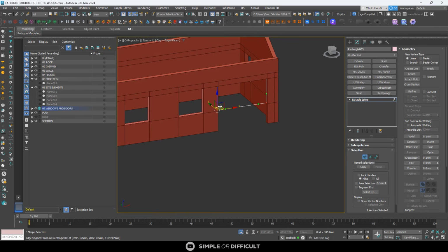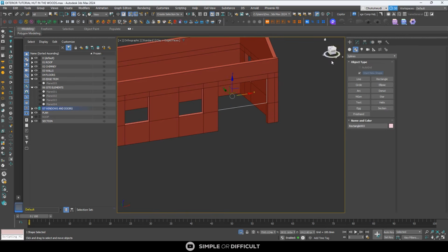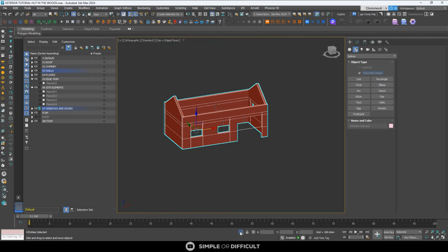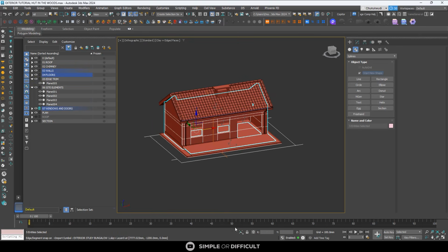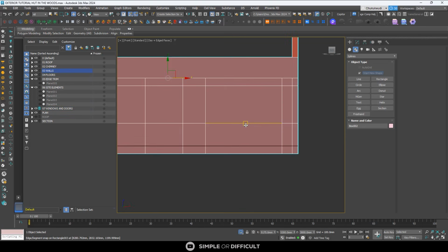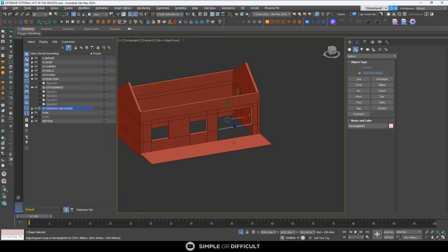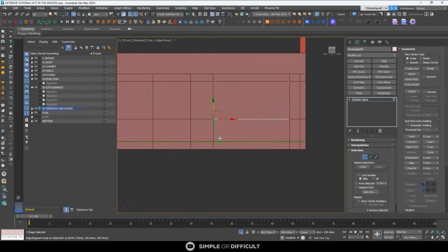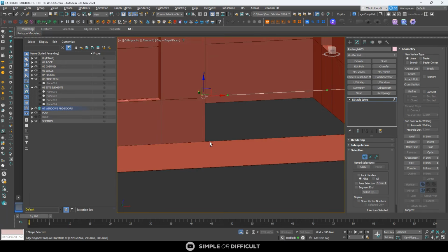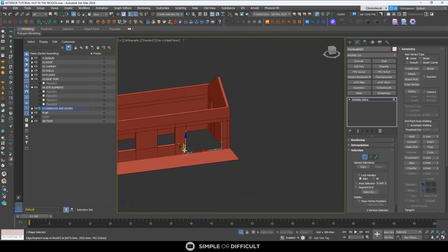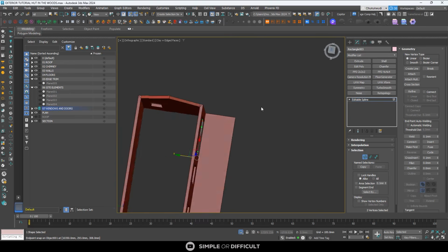Okay. I need this to be on the floor, so I'm just going to select everything. Then select this floor. So now with it being here, I can select this line. Okay, select that line and then hit 1 to be on vertex selection mode, then snap it. Right where we want it to be.